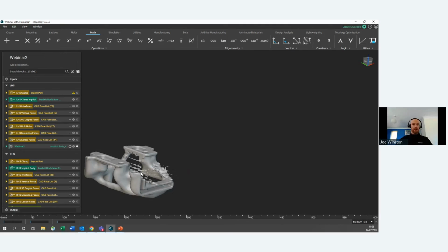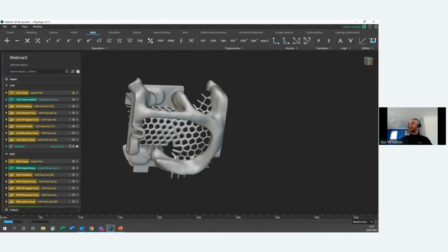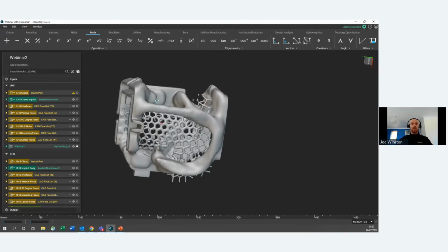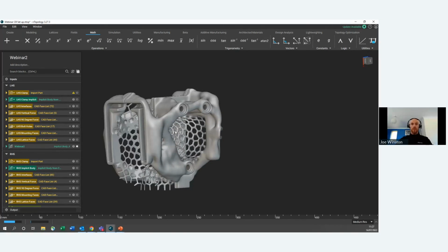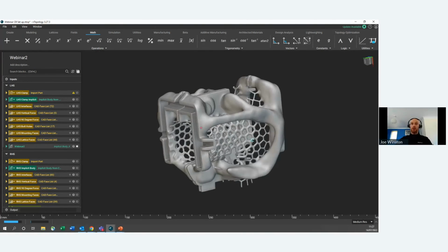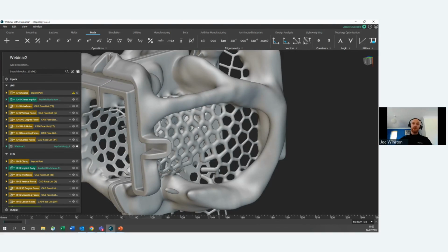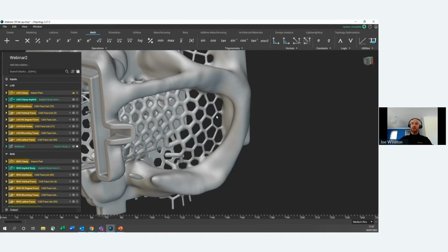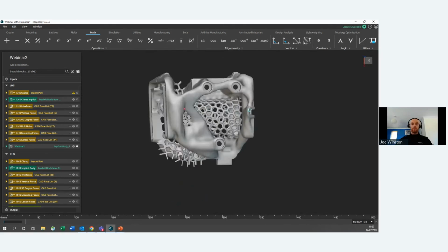This one is nearly finished, so that's the first half of the clamp that we were looking at. You can see kind of the power of the custom block and the workflow tasks that went into building the first one is done. And now we can just reuse this workflow and let it build it itself. You can see the results of the ramp block that we used here. So a much thicker beam thickness for the lattice in the middle where that sphere was, and a much thinner beam thickness as we get further away from that sphere.